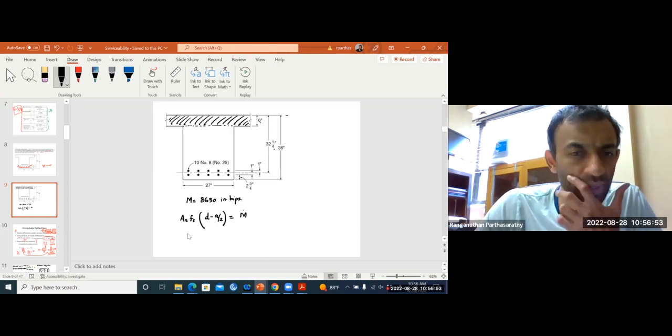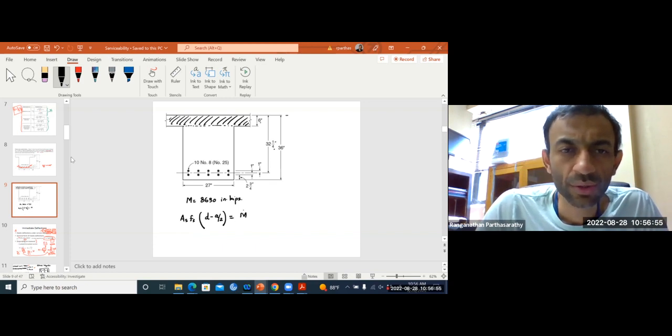So As, you have 10 number 8. So your As is 10 times 0.79 square inch.